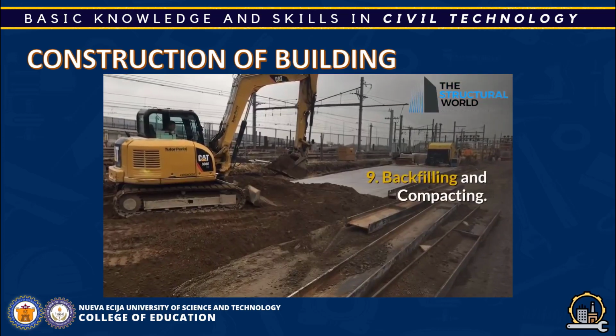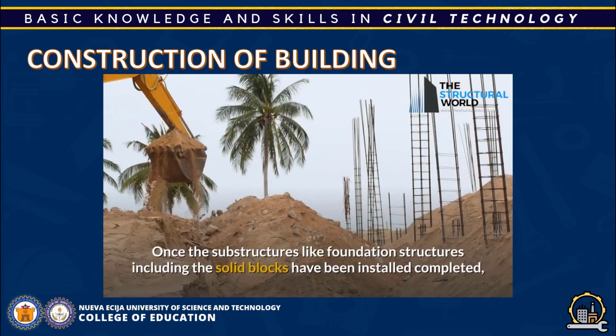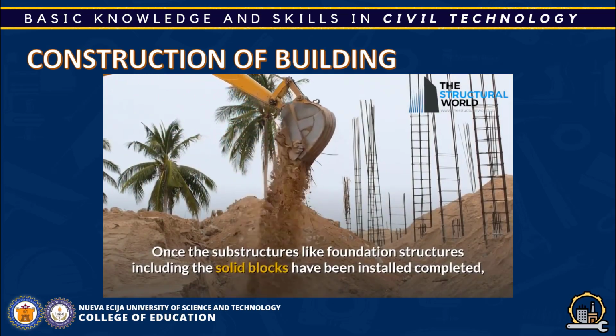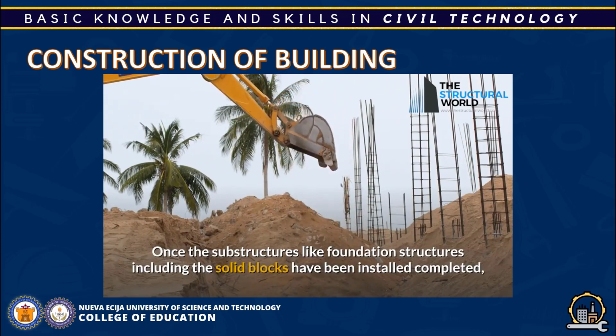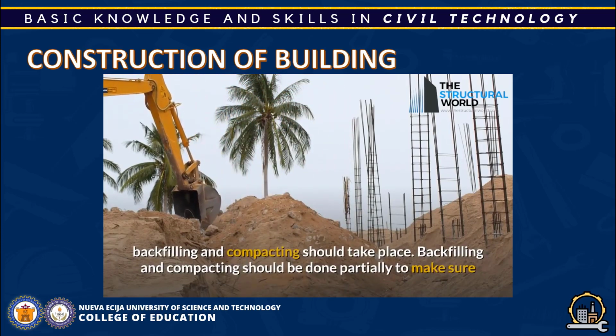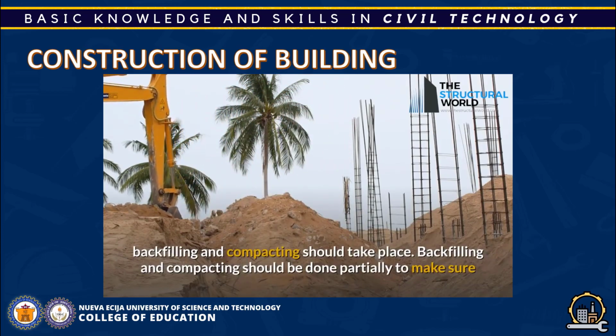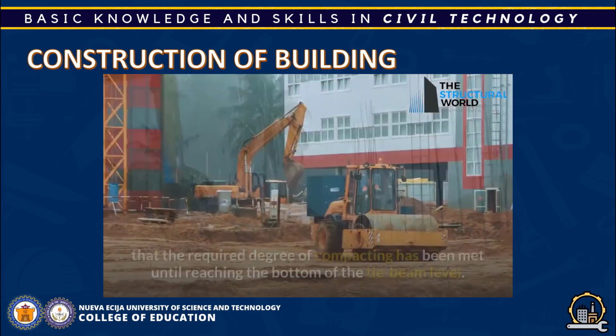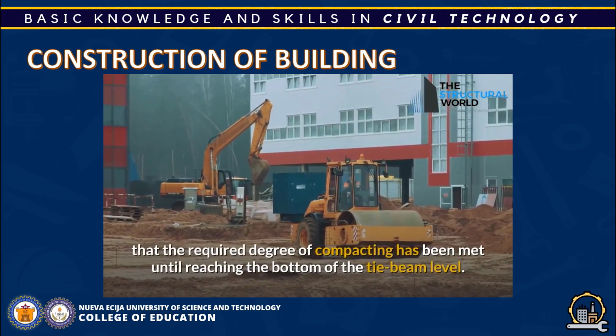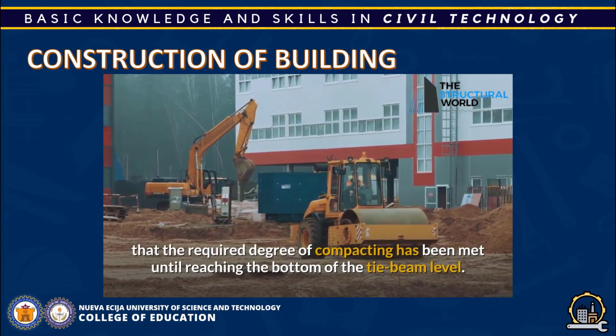9. Backfilling and compacting. Once the substructures like foundation structures including the solid blocks have been completely installed, backfilling and compacting should take place. Backfilling and compacting should be done partially to make sure that the required degree of compacting has been met until reaching the bottom of the tie beam level.